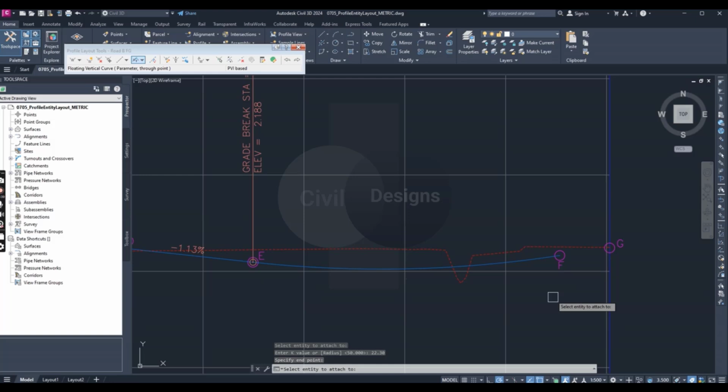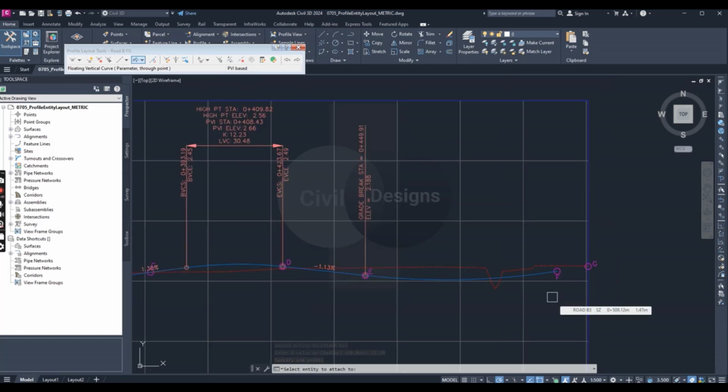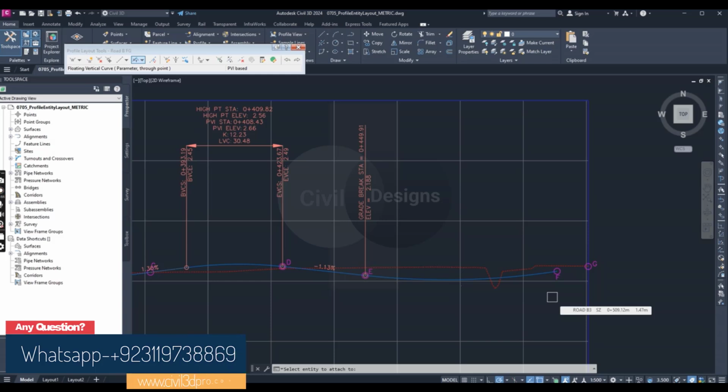You will notice that when using this tool, once you select the first entity and define the parameter, a rubber band curve appears. If you move the cursor on the wrong side of the tangent endpoint, it will become a larger red circle with a cross in it, indicating that you cannot select the point.